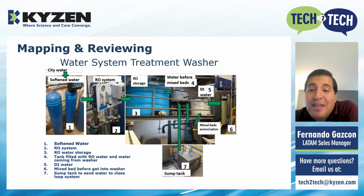We ended up having to map the entire water treatment system in the CM facility. We had to understand how water was being treated and recirculated along the entire system. In effect, the CM had a combination of RO system with a carbon and mixed bed filters and big containers where the DI water was being stored to have a buffer to feed the machine.